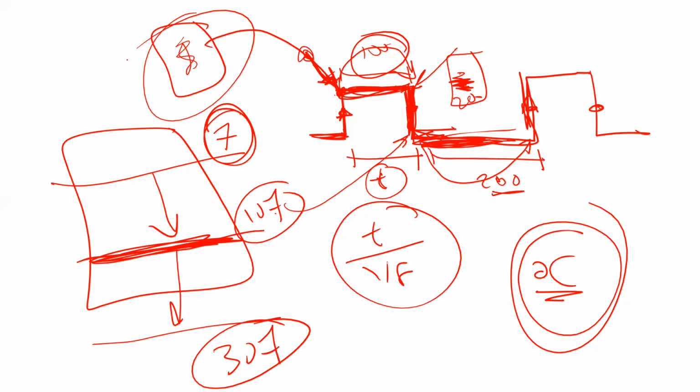Someone has to do the work anyway. So if the microcontroller doesn't do it, the external circuit has to do it. So the external circuit is going to count the time, toggle the pin, and interrupt you again in order to set the new count, how many counts until the next toggle.